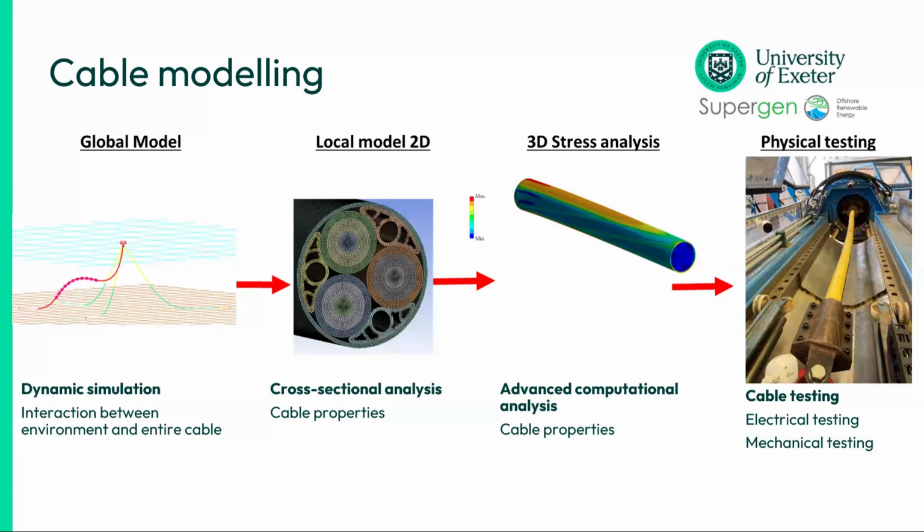And we've done a little bit of work to extend that into the 3D domain, which becomes computationally quite expensive, but gives a bit more information on how the helical lay affects the cable along one pitch length. And then on the physical testing, there's electrical testing, and then we very much focus on the mechanical testing of those cables to see what the actual load response is, and how does that correspond to the numerical models, which we can then update with some of those results.